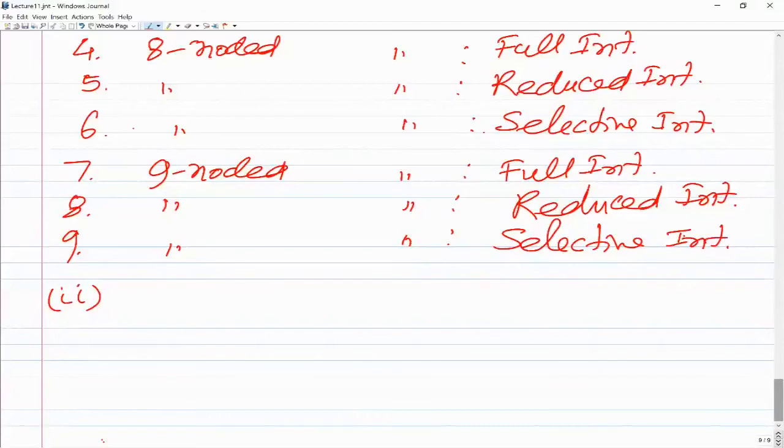Hourglassing control means we are applying some kind of nodal forces at the nodes of the element to reduce or eliminate the hourglass deformations, so there would be some energy corresponding to that. You have to make sure that this non-physical energy, which comes because we apply additional forces to control the hourglassing, is no more than, let's say, 10% of the total strain energy stored in the body. That is an issue we have to check when using software.